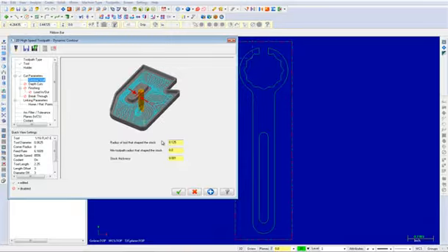The radius of tool that shaped the stock is the radius of the tool used in a toolpath that already cut this area. Mastercam calculates the stock to remove along the contour wall using the stock thickness, and, if provided, the radius of the tool that shaped the stock and the toolpath radius that shaped the stock. In our case, from the previous contour operation, you used a 1/4 inch flat end mill and no toolpath radius. Once the parameters have been adjusted, select the depth cuts.